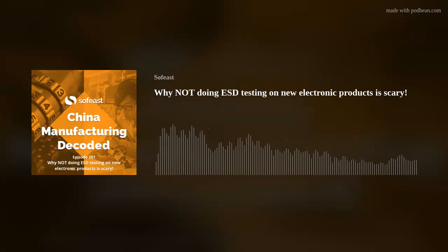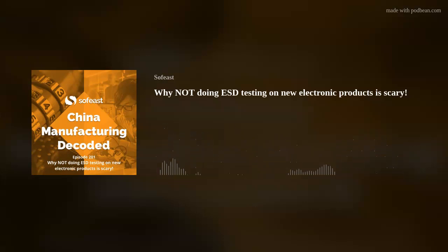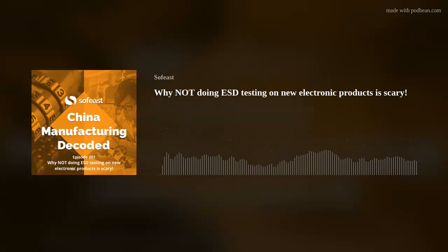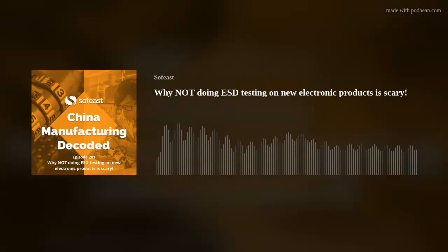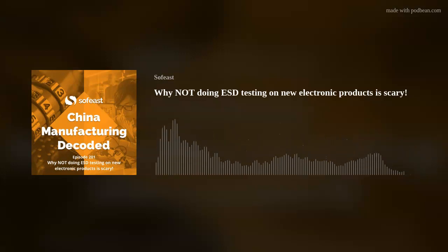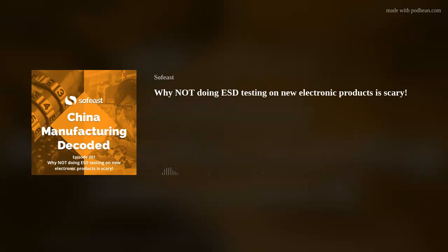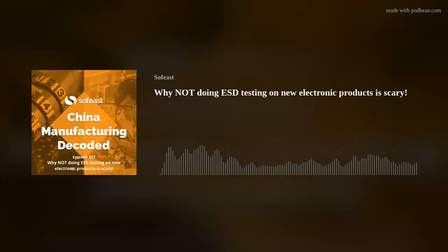different ways. Right. And of course, where electronics are concerned, this is not something that you want occurring within or touching your electronic devices if you can avoid it. Absolutely. Depends on what kind of electronics you have, but if you've got ICs and sensitive digital electronics, or electronics that for some reason did not have any kind of protection designed in, the high voltage, even though the current level is low, can actually cause a huge disruption, perhaps burn or melt your internal electronics. In the best situation, it might cause minor damage that you won't know about, or that might be intermittent until you've shipped the product.